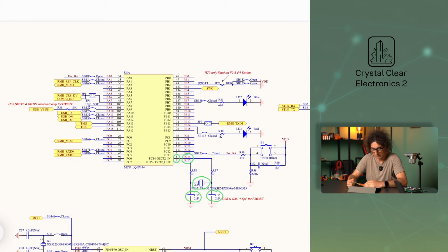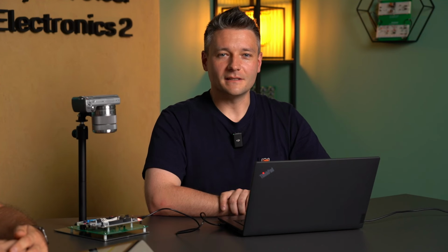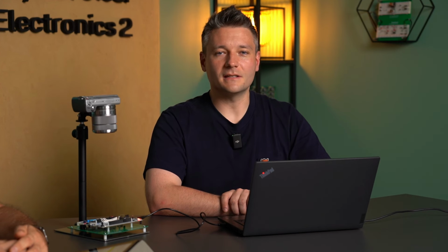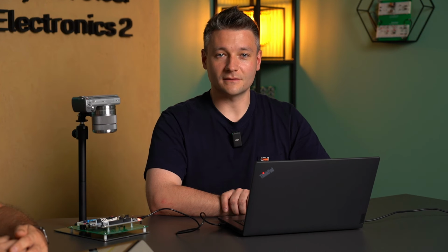The accuracy largely depends on the quality of the components used. For capacitors, it is advisable to use first-class ceramic capacitors with the lowest possible temperature dependence, which are usually designated as NP0 or C0G.